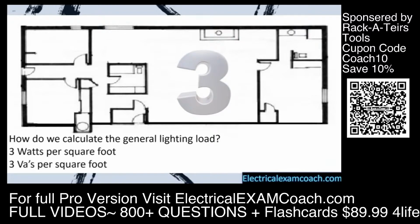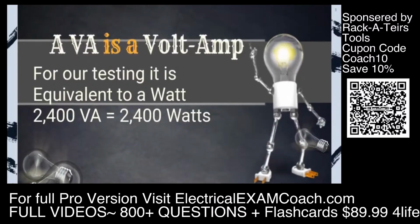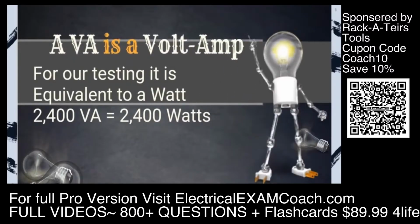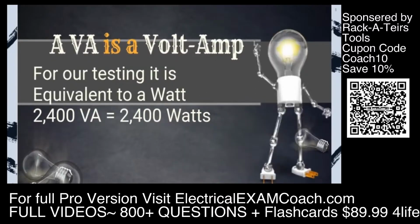But the code language actually uses VAs. So 3 watts per square foot or 3 VAs per square foot. But the question is, what is a VA? A VA is a volt amp, and for all of our testing, it's equivalent to a watt. So it's true for us to say that 2400 VAs is equivalent to 2400 watts. So for these calculations, we're going to be calculating them at 3 VAs per square foot.